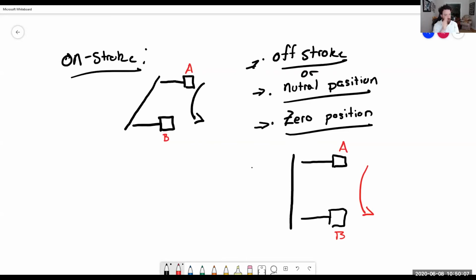So it's not going to be stroking along the x-axis here. The pump is rotating and the pump is on, but the pistons are not moving laterally, because there's no tilt.